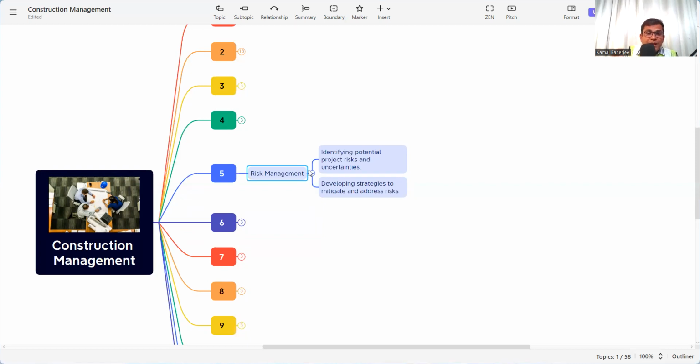In some areas where river sand is used, during the monsoon the river is closed and you will not get sand in that period. So how will you manage that? Maybe you need to stock before, or you need to find different material in order to perform the activities.